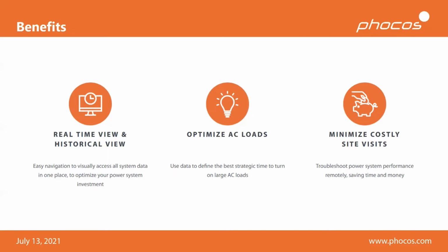In most cases, you will have to optimize for the worst months in the year. So typically for winter, wherever you may be located in that system. That does mean, though, that during the summer, you will have a lot of excess energy. So essentially, you will have too much energy. Of course, now it's important to manage your AC loads so that you can take advantage of that extra energy you might have during these midday hours or early afternoon, and to avoid running heavy loads, high consumption loads during the night when essentially you're only running off battery, or maybe if you do have a backup generator, running off a genset, which in turn will cost you fuel, etc., have emissions, all these things.